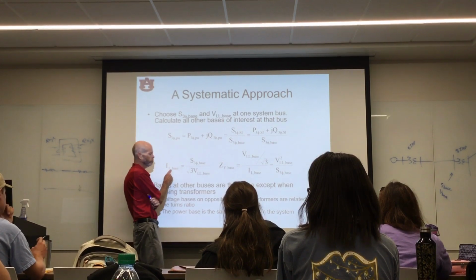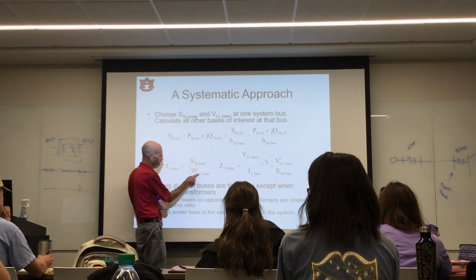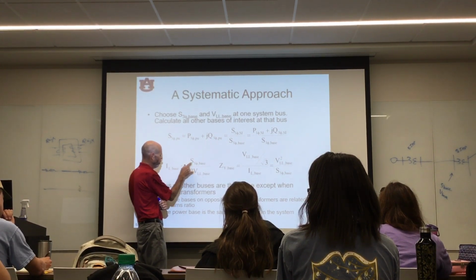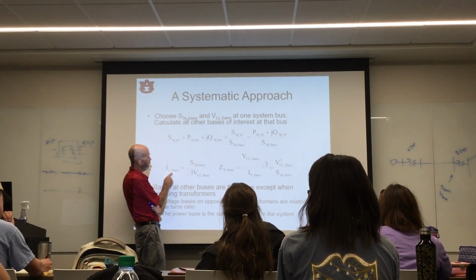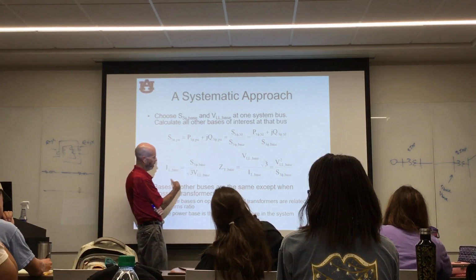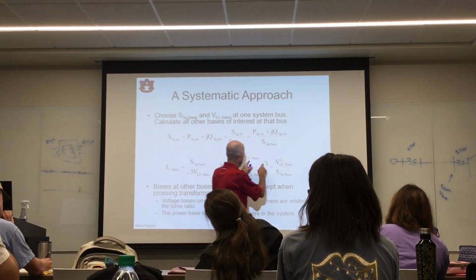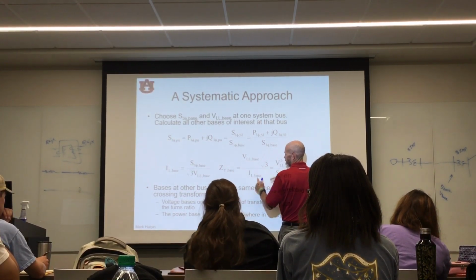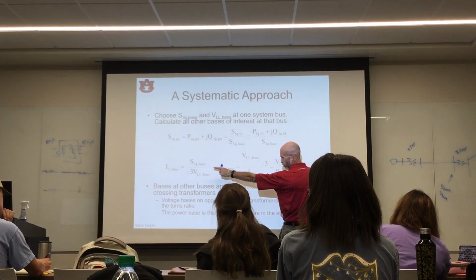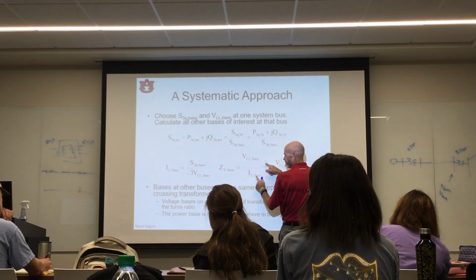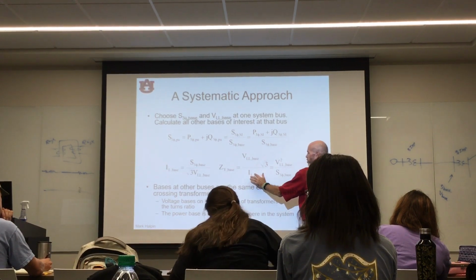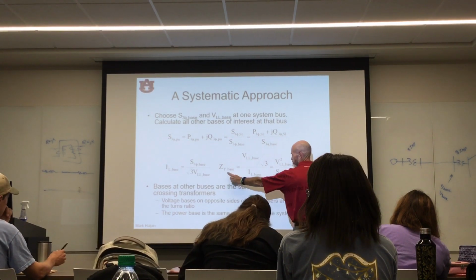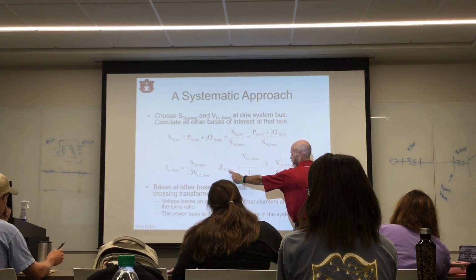Okay, here's the calculation for the line current base. These two I chose, right? So I've got these two. Bam, calculate that. Now what? Well, now I could calculate the line-to-neutral voltage base. There it is. And then I can plug in my result for the line current base.